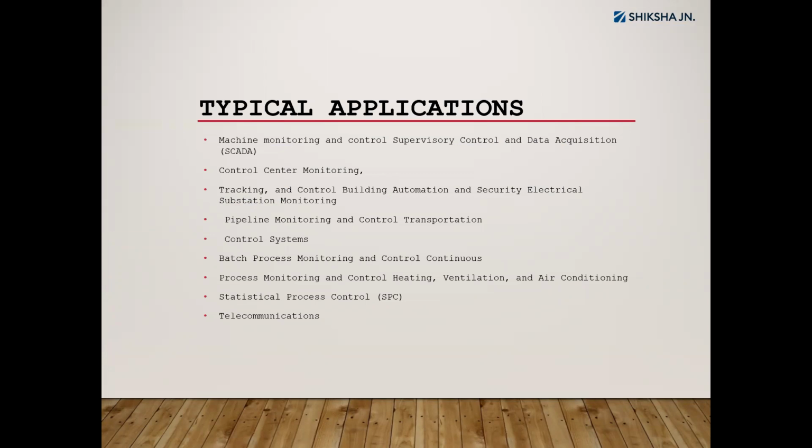Then batch process, as opposed to a continuous process. Just like a conveyor carrying the load continuously, the coal being carried out. In batch form, I have just passed the first batch of coal, then for the second batch I want to change the timing of the conveyor system, the starting time, stopping time. All these things you can operate from the HMI itself.